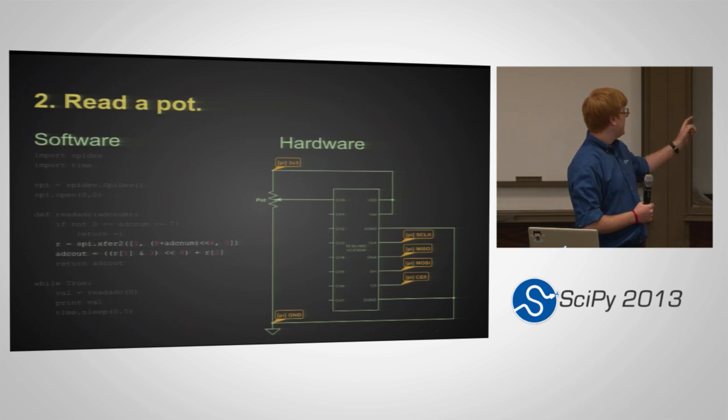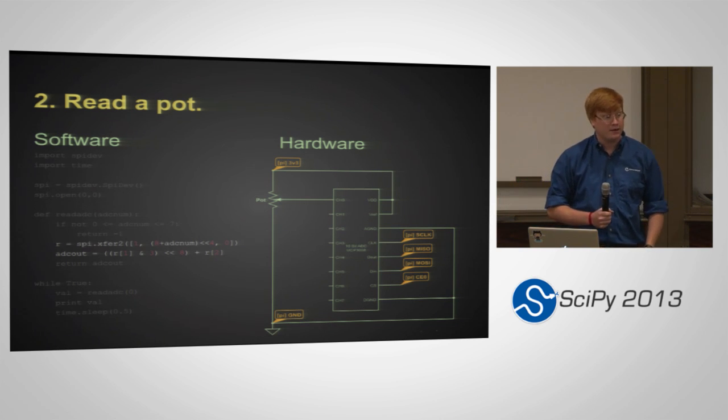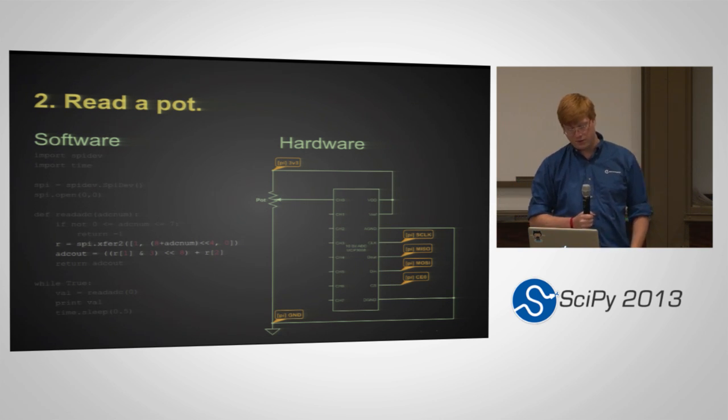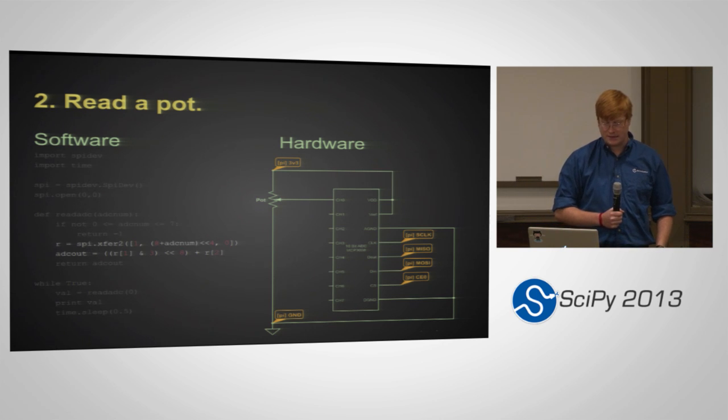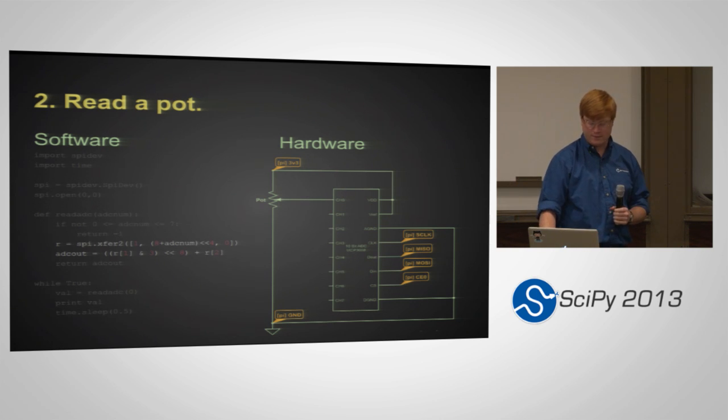And then the out value is grabbing just the 10 bits you need by ANDing one of the bytes with 3 to mask out all the upper bits, and then shifting that over and adding it to the lower byte. But that website I linked on two slides previous explains this in much more detail, exactly what's going on there.